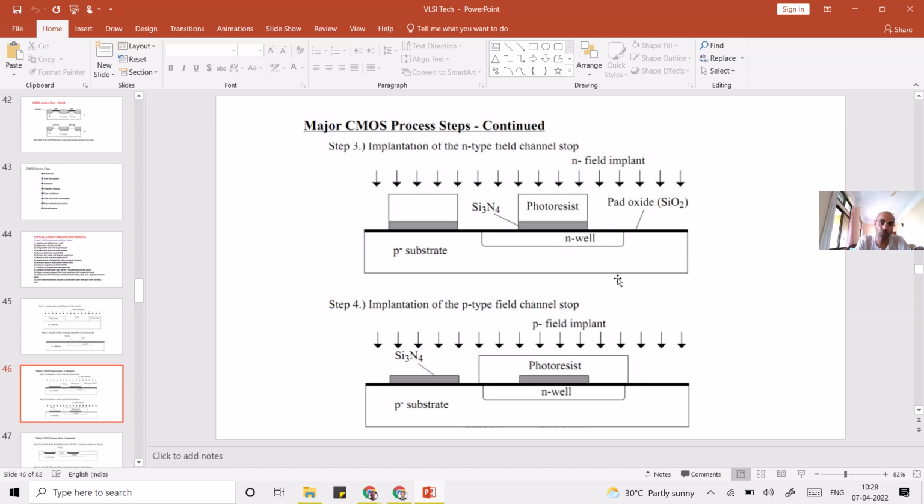So you are actually defining the active region in this case. You have to define the active region for both the N-well area and the P-well region. Why am I calling it the active region? Because when you see the layouts, you will see that the device cannot be very close to the boundaries of the well. They should be sufficiently apart to demarcate the difference between the two regions. So you need a certain separation between the boundary and the device closest to this boundary. For that we restrict the devices to be fabricated in a certain region in this N-well region. So we have to make an active area, and that active area is basically defined by this N field.